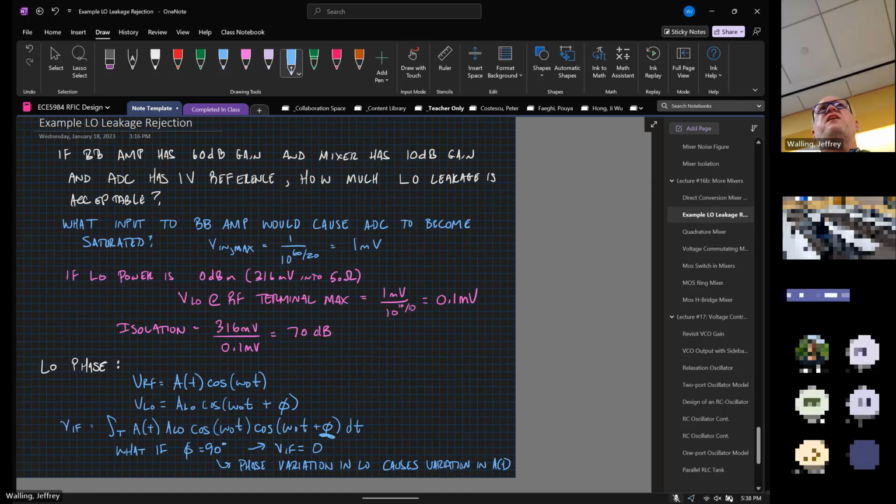So essentially what you're saying is we send a pilot tone in, we try and figure out what the phase is relative to the signal that's incoming, and then we maximize the signal. So like a calibration scheme where we adjust the instantaneous phase of the oscillator until we get a maximum signal, something like that. Yeah, that could work, but that takes some overhead in the signaling in order to be able to do that.